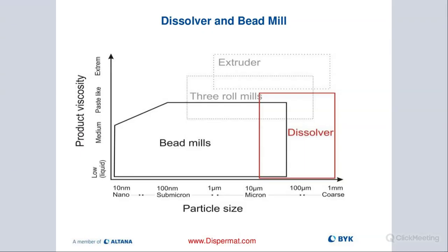So if you're looking for something below 10 microns of particle size, or even going down into the nano range, as we see with a lot of products like automotive coatings or battery slurries, then we also need to take a good look at the milling technology and understand what works best for certain particle sizes. But remember, when we are pre-dispersing, 10 to 30 microns particle size is where we want to go. And that would be sufficient with the cowles blade.